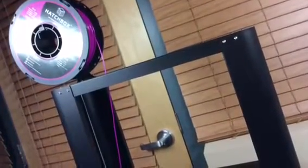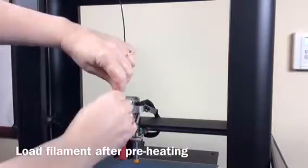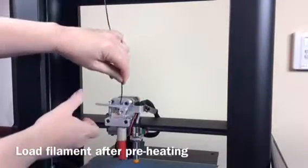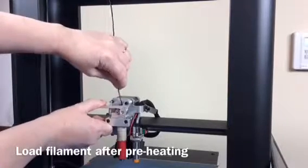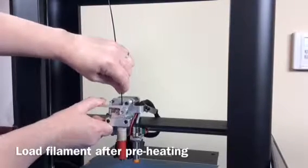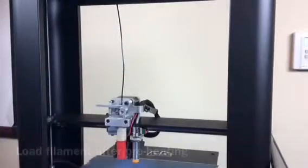The filament spool should rest on the holder on top of the printer. The filament should roll off from the top of the spool and then through the space at the top of the frame down to the extruder. Straighten the filament as best you can. To insert the filament, depress the lever and push the filament into the upper opening of the hot end. Once the filament is seated, release the lever.